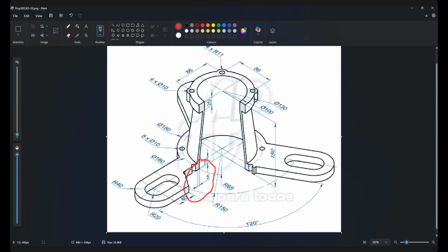The way I draw the arm, you are watching my Microsoft Paint, right? I will create a sketch at the front plane, not at the front plane. Actually, I will create another plane at that distance, parallel with the front plane. Then I will create a rectangle on that plane. Then I will extrude up to that surface. It will stop at the flange, the cylindrical object that we have just created.